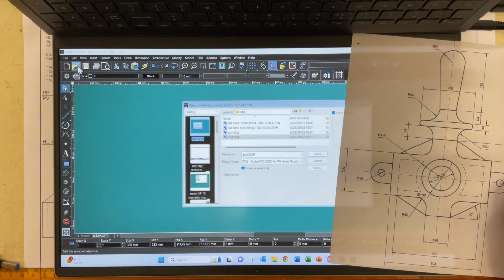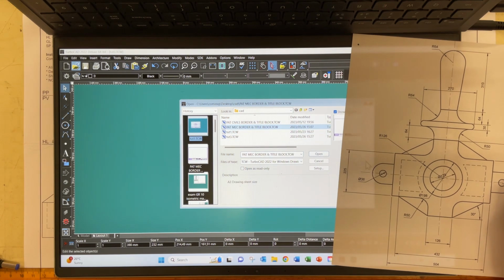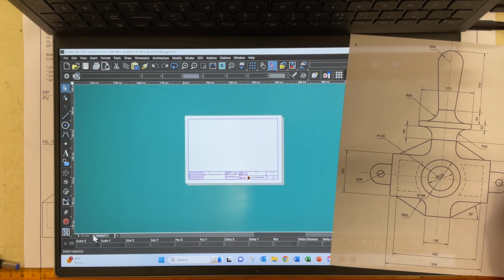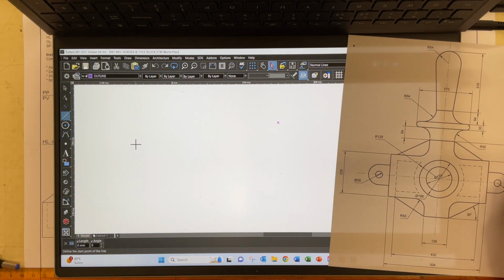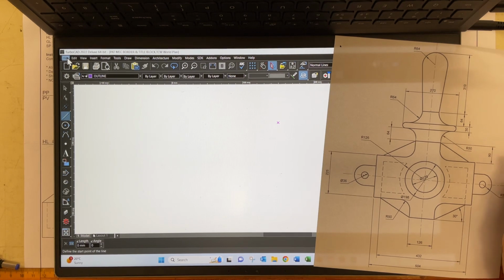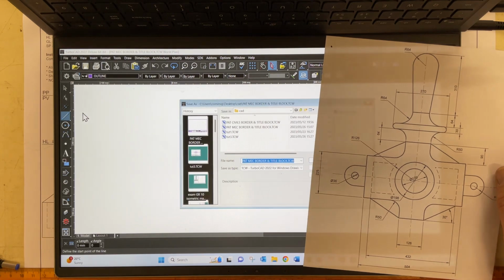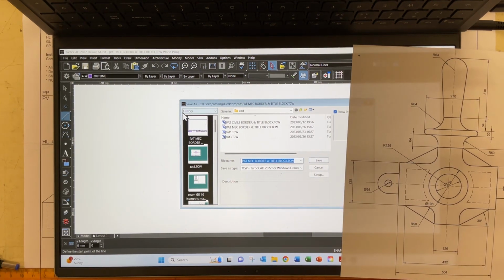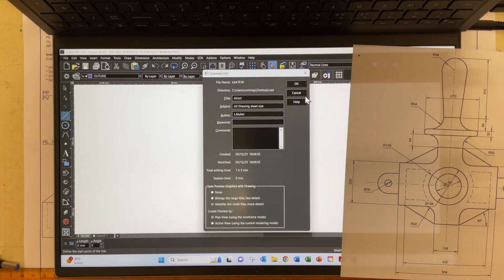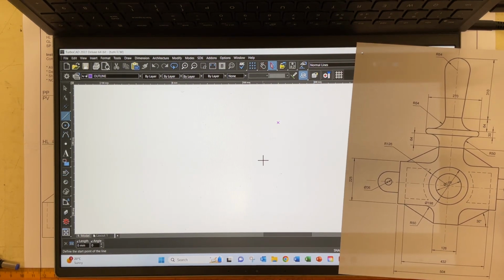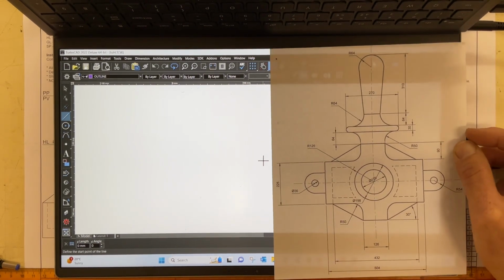I should then be able to go back over here to Mechanical Title Blocks and Borders, press Open, and guess what? It's a nice blank sheet of paper again. Go to your model space, it's a nice blank sheet of paper, and when you start the drawing, go in here and say Save As, and you can say TUT 4. Okay, press save and OK, and now you can continue drawing and you'll have this drawing saved as the next TUT.